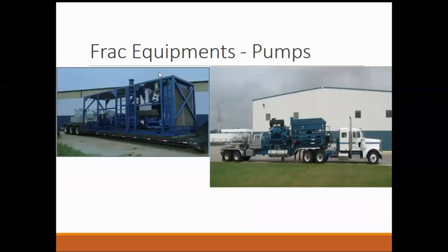From the blender, your slurry goes to the pumps. These are a couple of pictures of frac pumps. They increase the pressure of the slurry which is to be pumped in the well. And the selection of the pumps is dependent on a lot of parameters, as I also said before: your size of completion, your type of completion, what formation you are dealing with, what pressures are required for fracturing that formation.